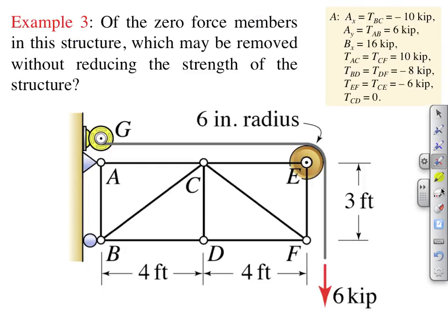Here we have a truss examined in section 6.1. We noted then that member CD is a zero-force member. We also determined as part of our analysis that members BD and DF were carrying compressive loads of 8 kips. In this case, we would not want to remove CD, since it would decrease the critical buckling load of what would be BF by a factor of 4 relative to BD or DF.